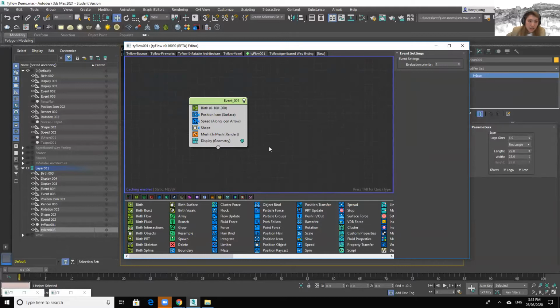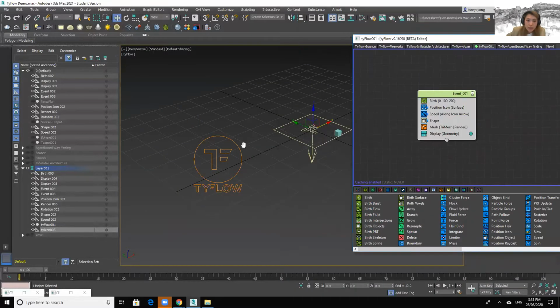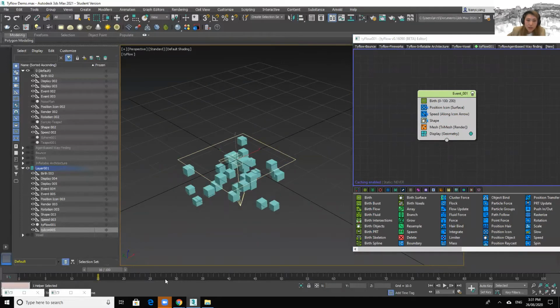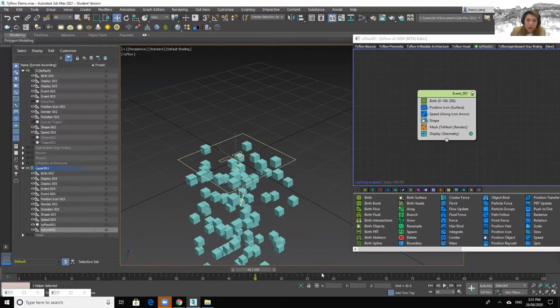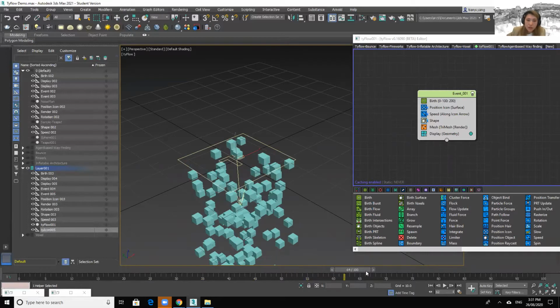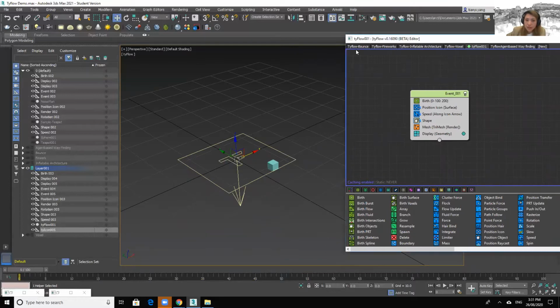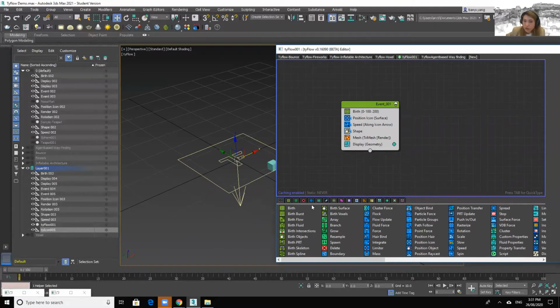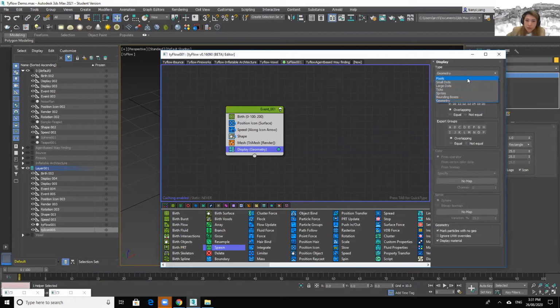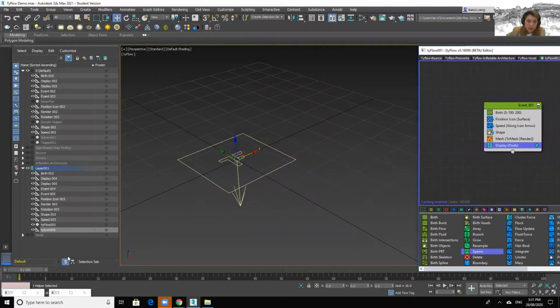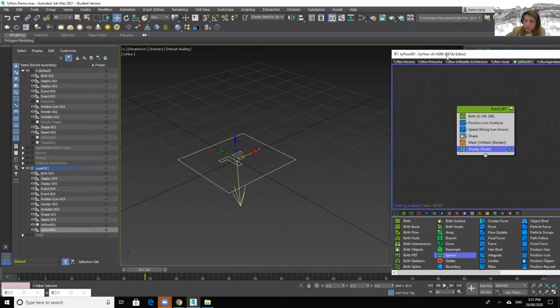And what this simple preset flow does is create several particles and make them follow the icon direction and drop. So let's take a closer look at this. If you look closely at these operators, you can find them in different colors. Basically, the concept is that all the things in green create some particles. So let's change the display to pixels. Those are the particles you created.